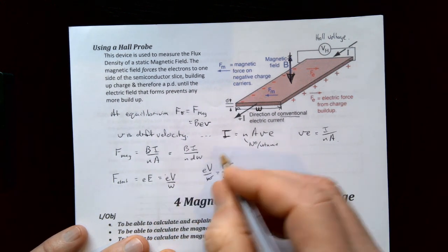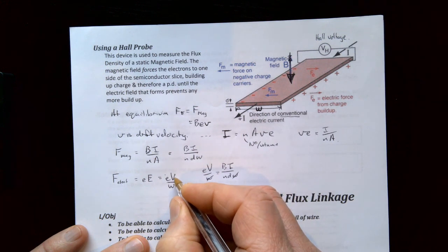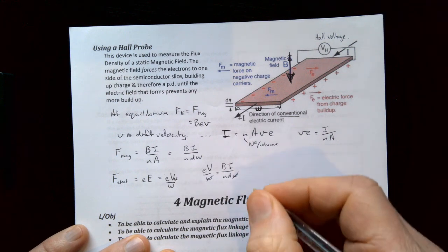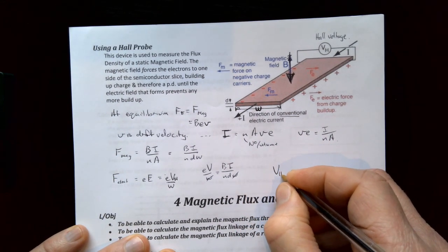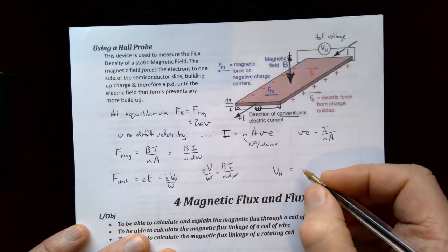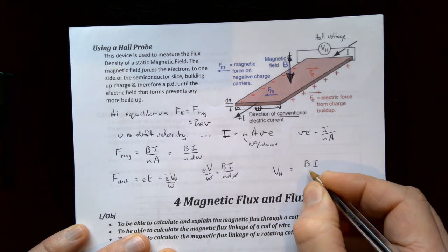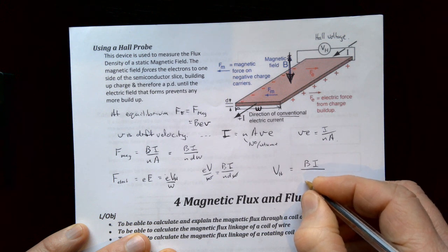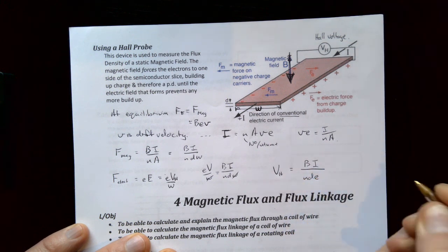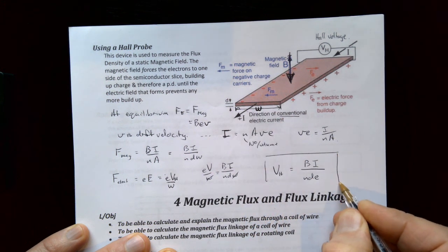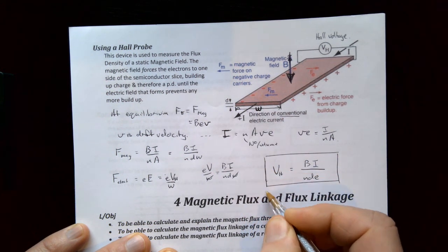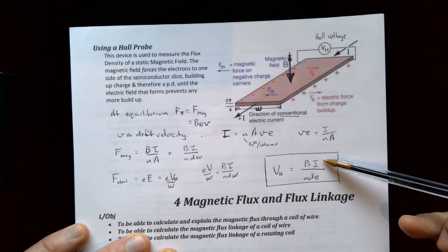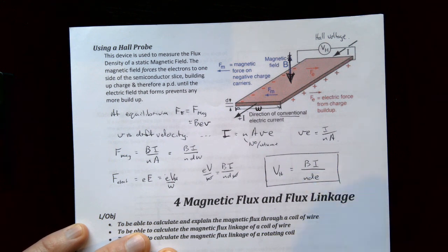So just going to pick up with our symbol up here. I'm going to change that to H because that's what I'm after, my Hall voltage. So I'm simply going to have our final equation, which is the voltage that is measurable with our voltmeter. It depends on B, depends on I, because if they're flowing faster they're going to get further. And then ND, let's stick it that way, NDE. So that is really about the only way we can measure B, flux density. We need to know the current, and the rest is just dimensions and known values.